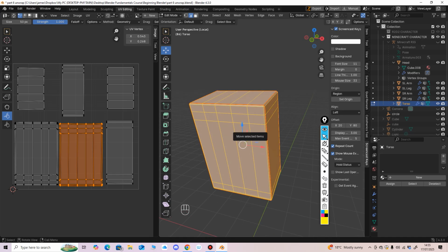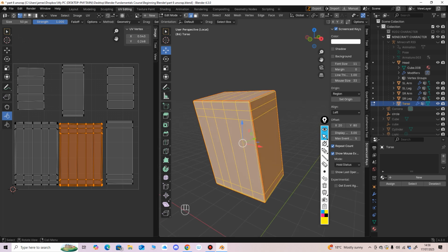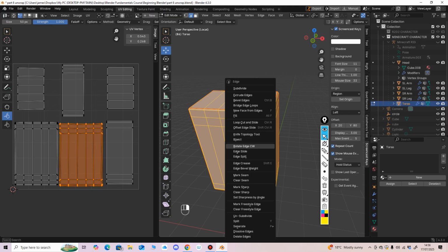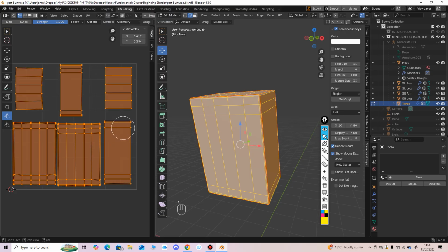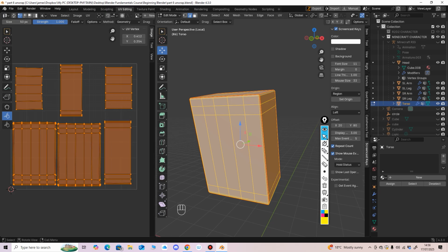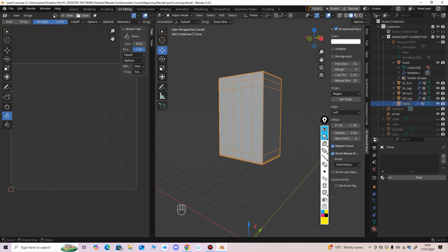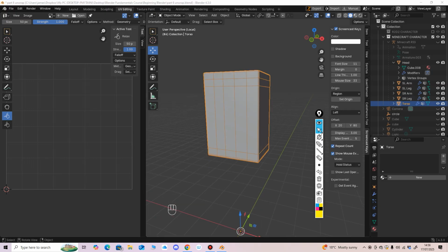There's probably 5 or 6 core options in UV editing as well that you'll use, like obviously your marking seam, U to unwrap, right click, which brings up your seams. But yeah, just probably 5 or 6 core options, really. You can unwrap as well by right clicking in your UV editor. But that is basically the basics of unwrapping.